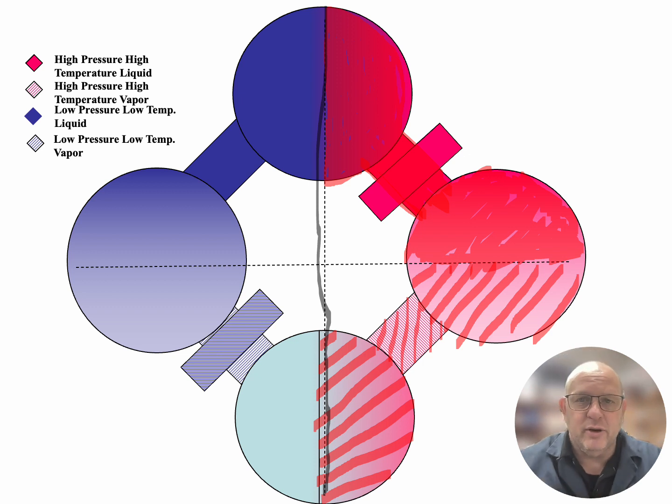It's sending the refrigerant through a really small hole, high pressure on one side, and then expanding it. And that's one of the reasons why they call it an expansion valve, because that refrigerant, as it's going through that really small orifice on the metering device, will expand into a very large area. And the pressure of that refrigerant will go from high pressure to a low pressure. Now, when that happens, the refrigerant temperature will also drop within that system itself.